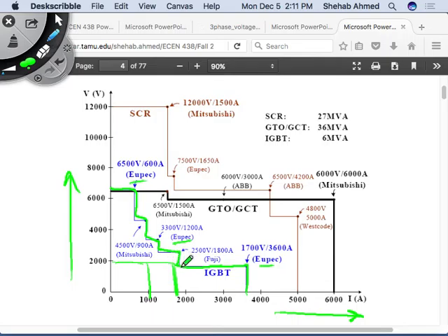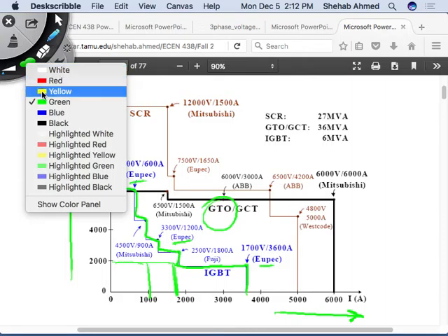So if you don't find an IGBT, that means you cannot use sinusoidal pulse width modulation and switch it many times per cycle, because you're going to end up trying to go to a GTO type device. We will look at the speed of these GTOs, which are basically what? A thyristor that we sort of converted to be able to turn off as well. I think I briefly touched upon that at the very beginning. So we will look at the speeds of these devices, but generally, MOSFETs will be right here.